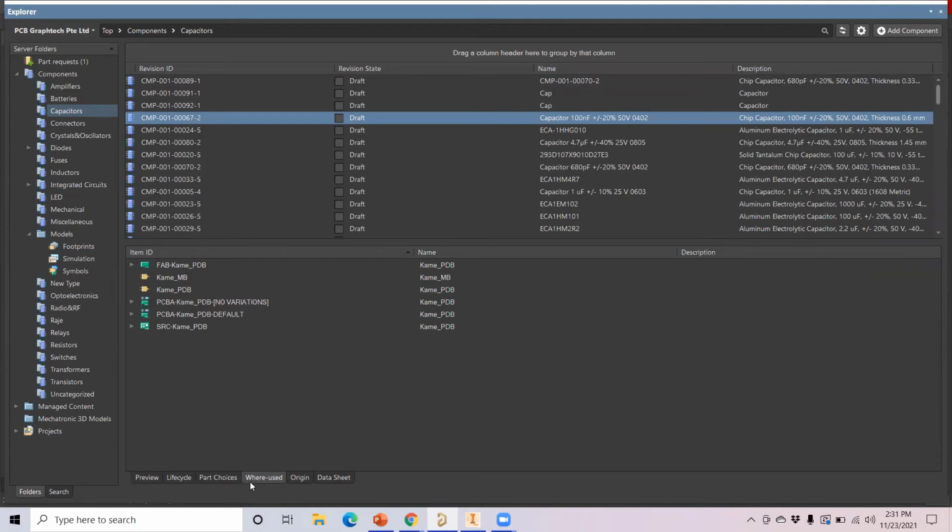This is a very good feature we have, where all this component has been used. Under your PCB document, under this PCBA COME document, all these documents, I'm using this component. The drawback is only based on the footprint, because the footprint pin is bad. I want to change only the footprint.